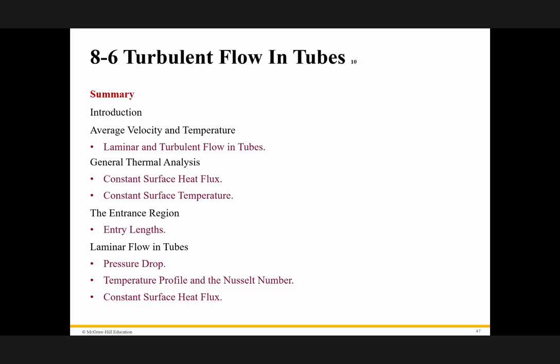Therefore, now we have more or less complete information on how to calculate heat loss, heat gain, or air conditioning load, because we have knowledge of conduction. We have knowledge of how to calculate the convective heat transfer coefficient. One part is still left for later, natural convection. This was forced convection, meaning an external source pushes the fluid, such as a fan, a pump, or the wind. Later, we will study natural convection,